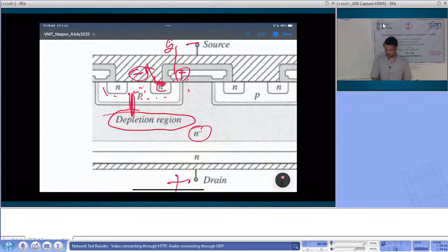Okay, so now if you have a 1000 volt device, that would have a much higher on state resistance because of the large N minus region, right, which you have to use if you want to block a 1000 volt device.